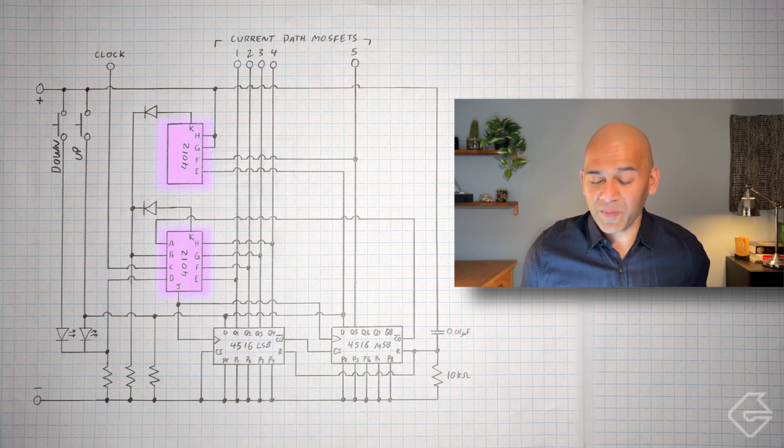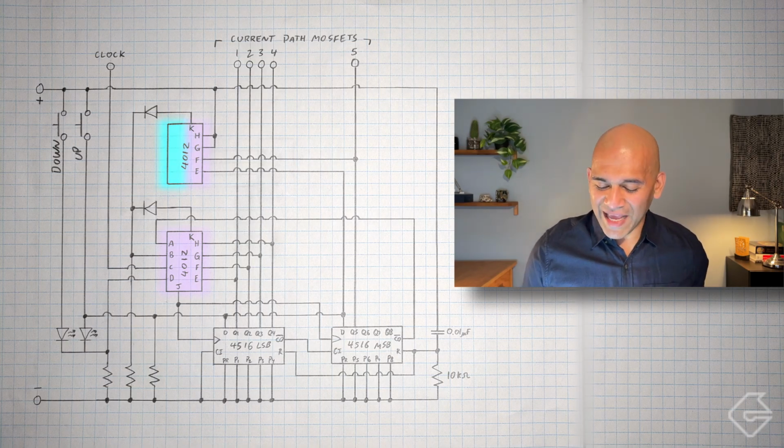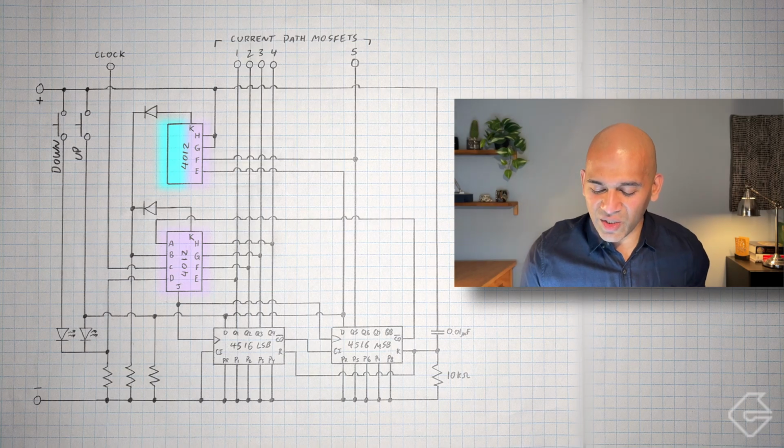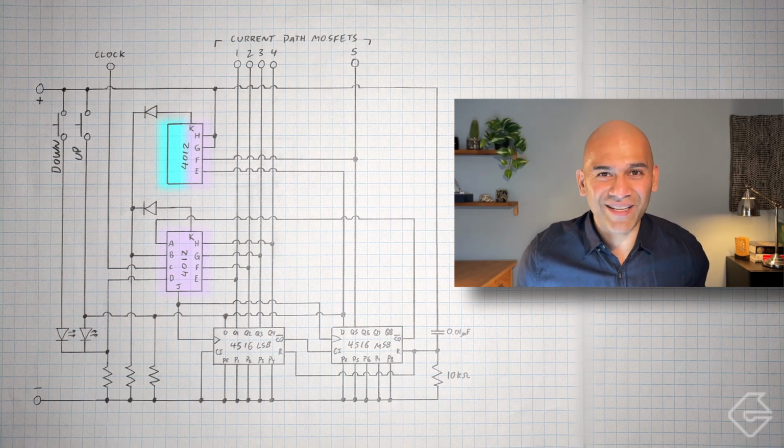This particular chip, we ended up using both of those gates, but this chip, we only used one, which left the other one available for us. And these chips happen to be CMOS chips. So the output of every CMOS chip looks just like that arrangement you saw earlier, which means I could use this NAND gate as a CMOS inverter, and that will help us accomplish exactly what we need to do.